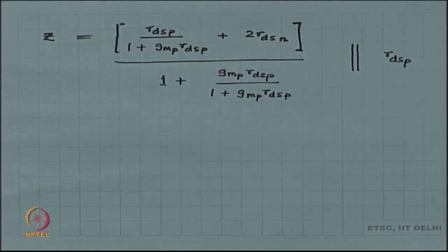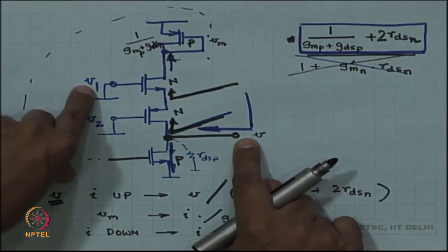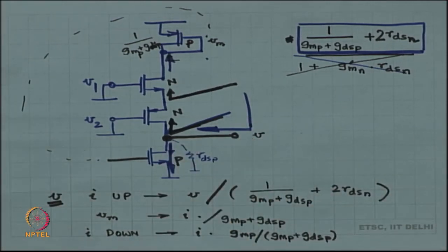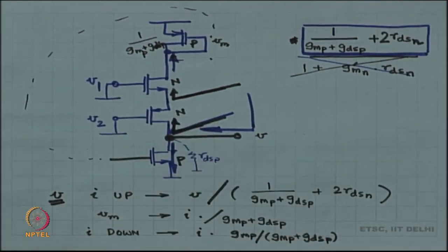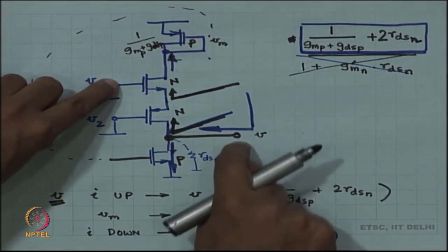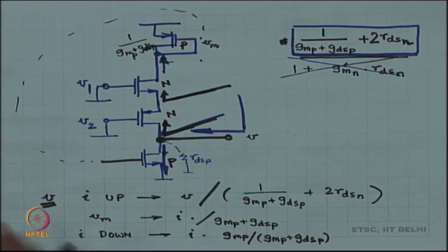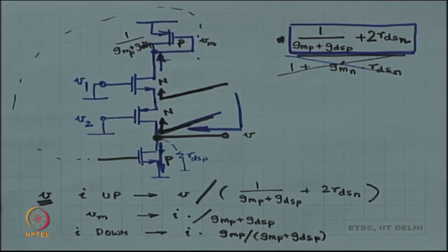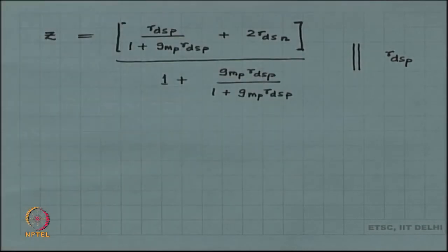This is the impedance looking in, and this experiment is going to suffice for both application of V1 as well as application of V2. For both you get the same answer. Okay. So, two experiments in one shot, the output impedance. Then we are going to apply V1, measure the short circuit current, apply V2, measure the short circuit current, and then finally we will see the net response when I apply both V1 and V2 at the same time. This is the plan. This is the first experiment in the 3-part experiment, first part.